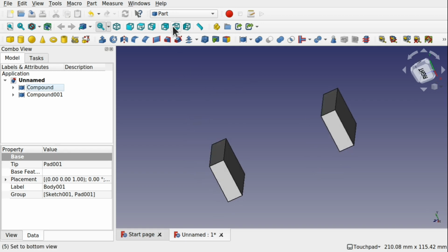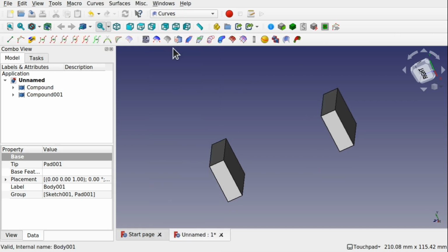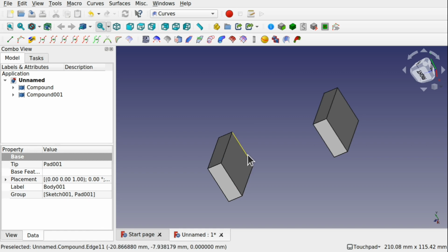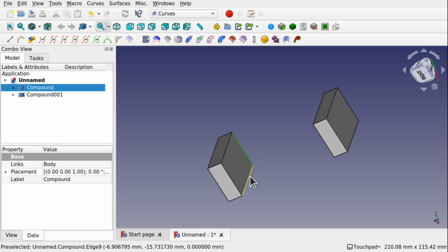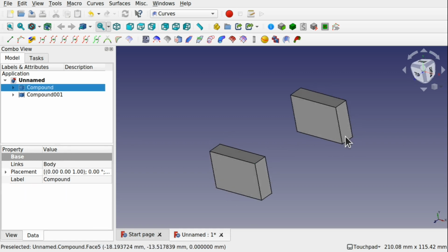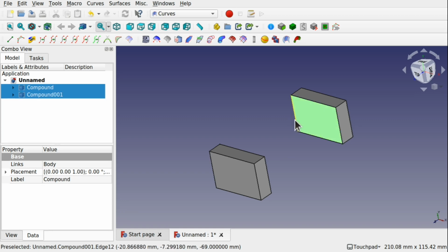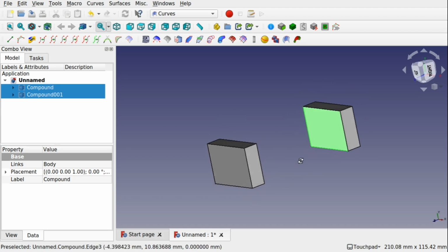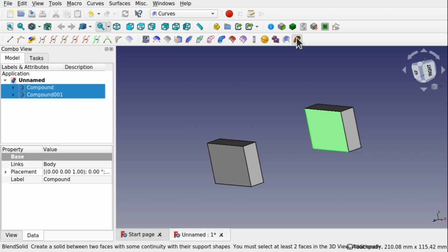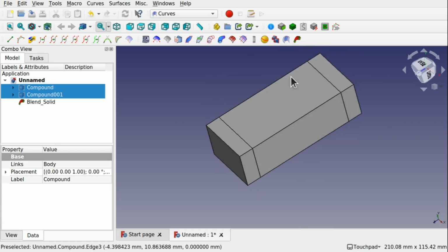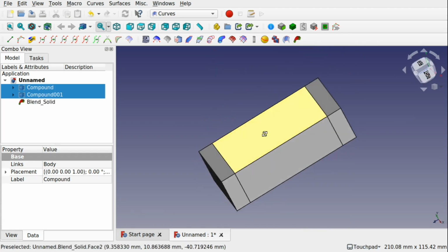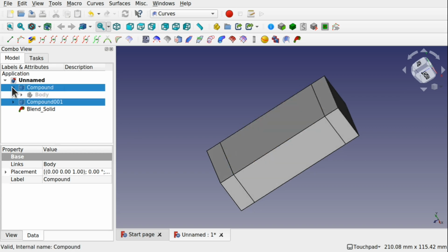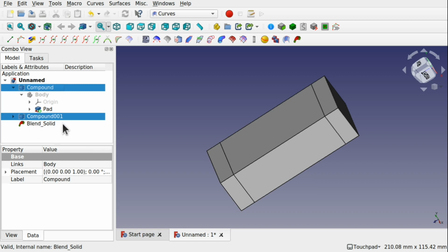That allows me to come over to the Curves Workbench and select an edge, say the back edge and the bottom and that face, the back edge and the bottom, showing that the order that you select these in, as long as they're the correct edges and the faces, it won't cause any problems. And we'll use the blend tool. So you can see that if you're using the part design, you'll need to actually create them as compound objects for this to actually work.